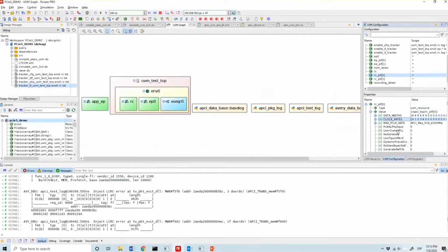And there's different modes that you can also configure, things like configuring the P clock as a PHY input, which is supported by the pipe spec, or generating a reference clock for a design. You can configure it as a low pin count mode, and you have several other controls, and you can also, of course, see all of the different pipe interface signals in here and directly jump to the waveform.